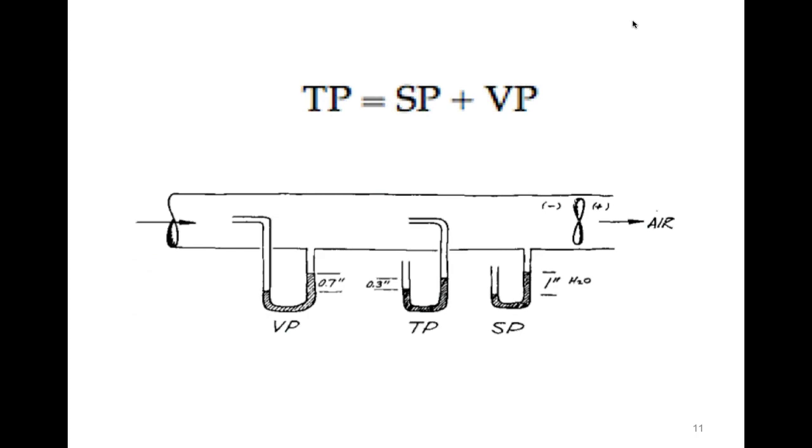So that tube levels itself out. The height of that water in that tube is the same height, no matter what's happening in the rest of the world, right? When that fan goes on, the upstream side of this fan becomes negative. The pressure becomes negative.